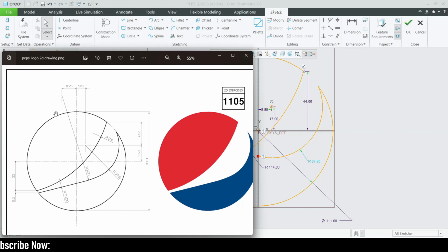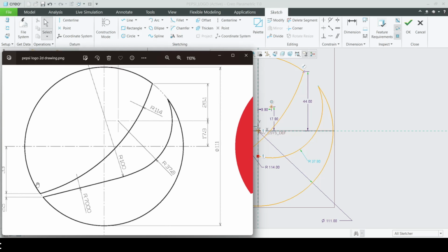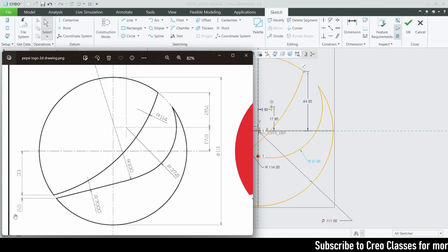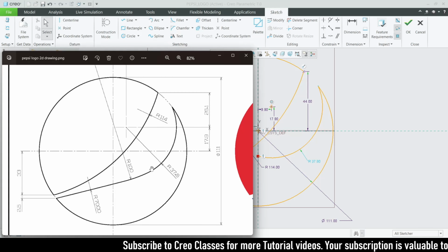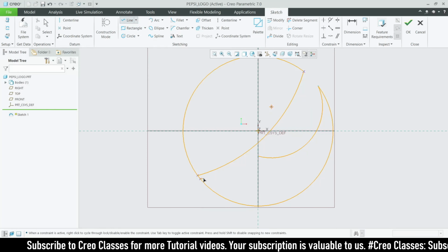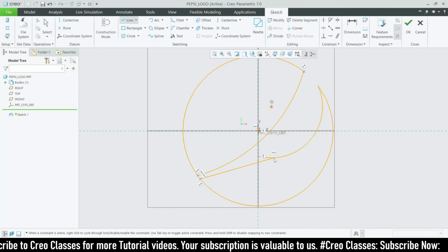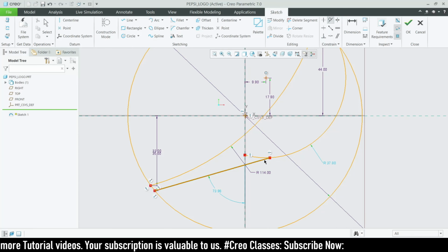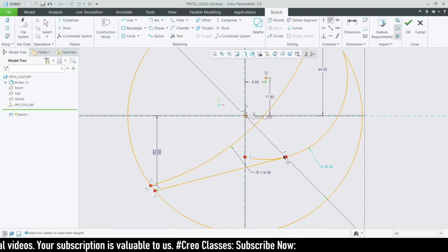So instead of that, I thought of having this arc directly continue with a tangent, which will be coincident with this 2.5 point. You can see here, this will be a straight line and it will be directly coincident with this arc, like a tangent feature. So let me create a line like this, and now I can make this tangent like this and like this.